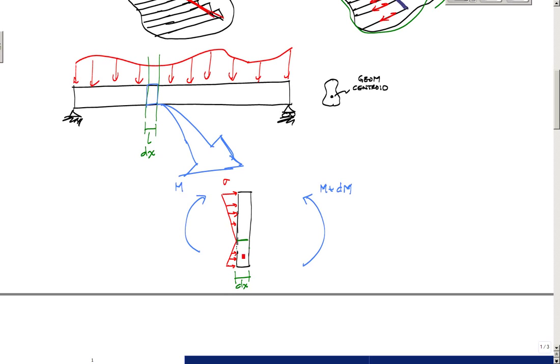And then over here, if it's increasing, I'll just draw a little bit bigger, assuming that it's increasing. This would be some other stress, sigma prime. I got to put one side in tension. So let's say the top is in compression, and the bottom is in tension, like this. And then same thing here, in tension, okay? And on this side, anything above the neutral axis is in compression. And here is my neutral axis, which also represents y equals 0, right here, okay? And plus y would be defined this way, right there.